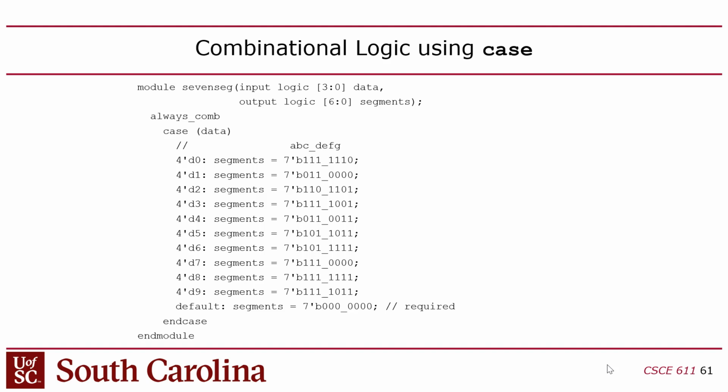That's 1. 2, if you look at the manual for the FPGA, which I linked on Dropbox, the 7-segment decoders on here are ordered from least significant to most significant, whereas these bits are actually reversed, right? So in other words, the A input on the 7-segment decoder is the top segment, and it's the most significant bit here, whereas on these FPGAs, it's the least significant.